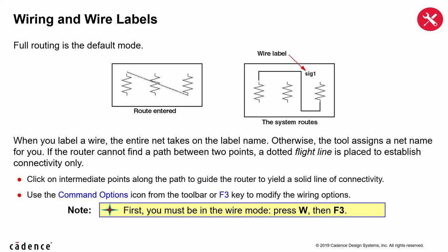You need to draw wires between different instances and from pins to instances to create connectivity and establish design logic. You can create narrow or wide wires in the schematic. You can use wide wires to indicate multiple signals on a wire. The system does not force or check this. You can draw wires at any angle, but most designers frequently restrain wires to orthogonal lines.